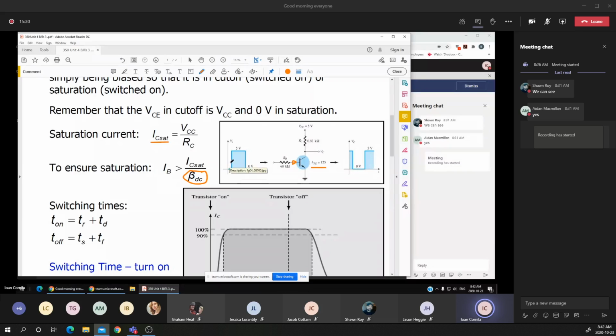Suppose that for this interval, the input voltage is equal to 0, which makes the VC, or the voltage at the collector, the maximum voltage because the transistor is in the off state. That means there is no current flowing through the transistor, so the voltage at the collector equals the maximum voltage, which is the 5 volts supplied voltage. When a voltage like 5 volts is applied to the base, there is a current supplied to the base of the transistor.